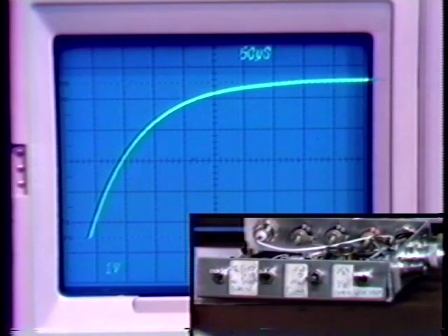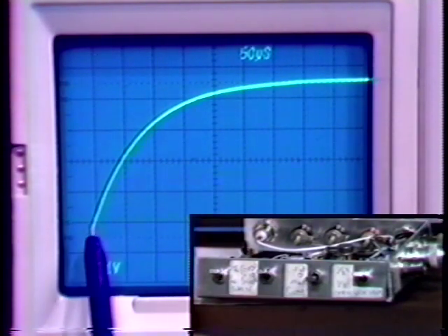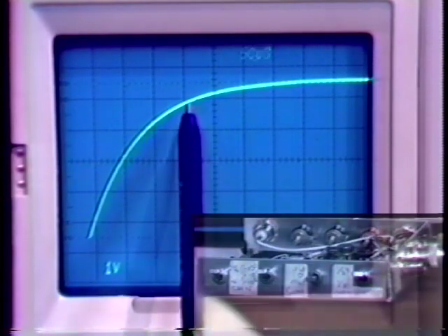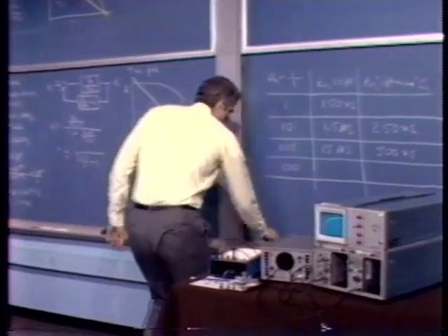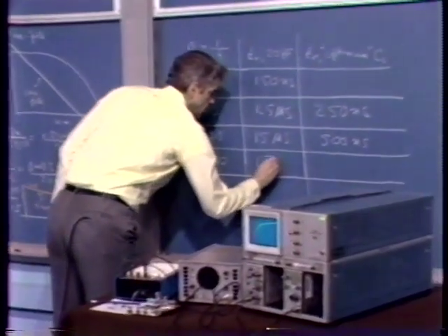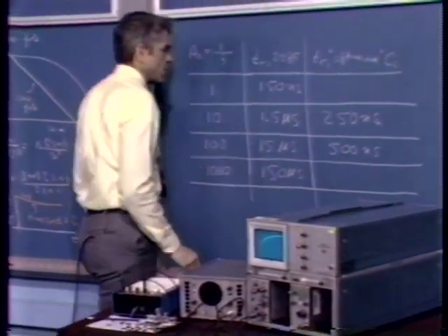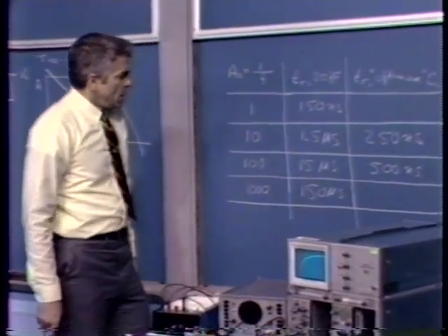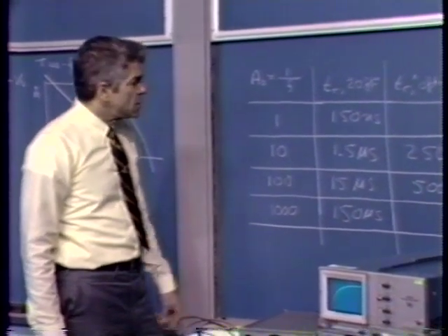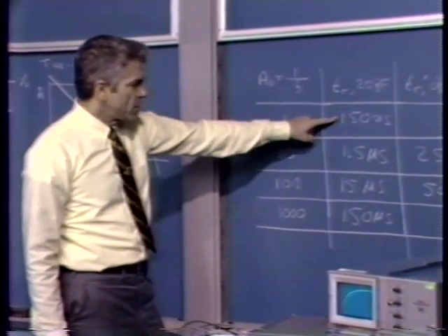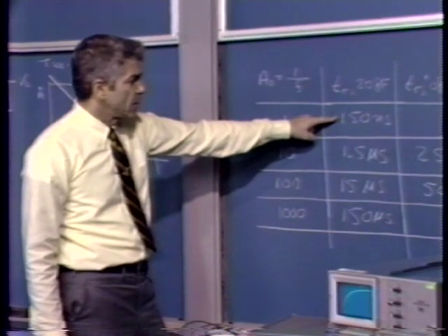And if we make the rise time measurement this time, let's see, we're at 50 microseconds per division. So we have 1, 2, again, just about 3 divisions for the rise time. So we have a rise time of about 150 microseconds. Our amplifier, as we anticipated, has gotten a factor of 1,000 slower than the original case. If we interpret this in terms of bandwidth rather than rise time, here we had a bandwidth of very nearly 2 megahertz, or actually a little bit more.